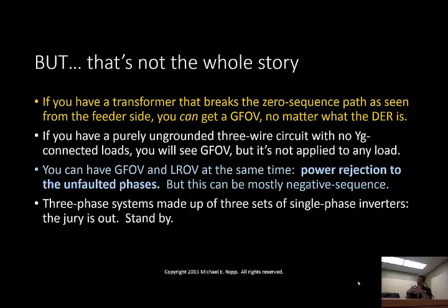You can see how this starts to get really tangled up in a hurry. So we're going to talk about that in a minute. The reason why it's important to separate those is because when that happens, it's not necessarily zero sequence. You can have a big negative sequence component. So the mitigation changes. That's the reason we have to keep it separate.